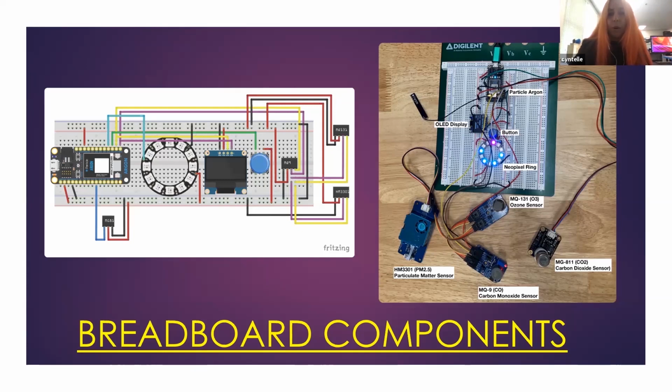We have the Particle Argon microcontroller, which was great to use because of the Wi-Fi connectivity. We have the 4 sensors that Ted mentioned in the previous slide. The 3 I2C sensors are all wired on the same bus. We also have that single analog sensor.